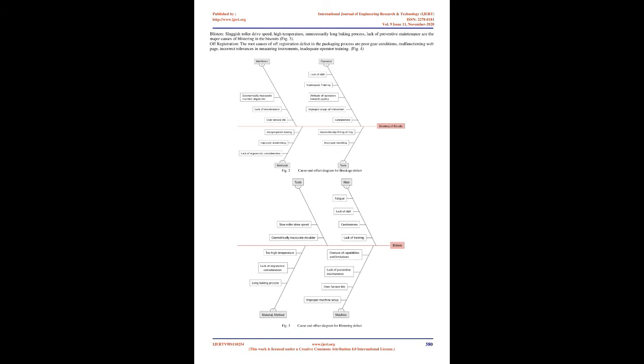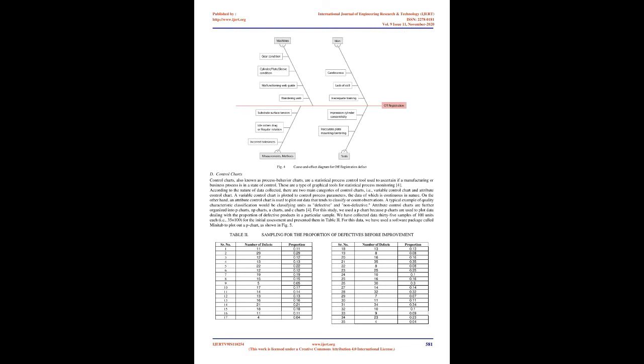A. Data collection. In the next step, the sampling of the product was done for 6 weeks. This allowed us to calculate the final product's rejection rate due to each type of defect, as shown in Table I. B. Pareto analysis. Based on the 80-20 theory, Pareto analysis is a method used for corporate decision-making. It is a technique of decision-making that statistically divides a small range of input variables, either beneficial or unfavorable, as having the greatest effect on an outcome. The Pareto analysis is based on the premise that 20% of the work will produce 80% of the gain of a project, or, conversely, 80% of the issues are attributed to 20% of the causes.